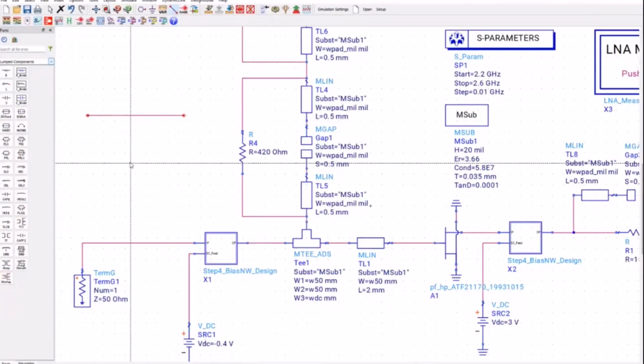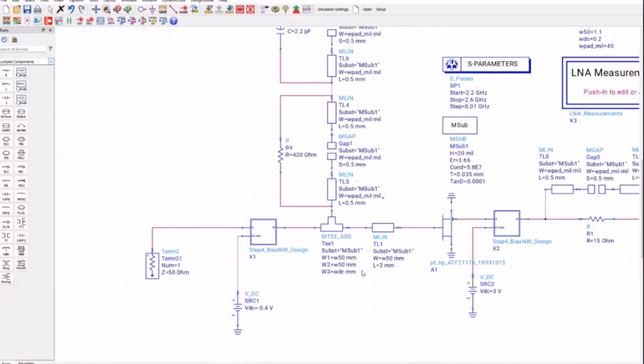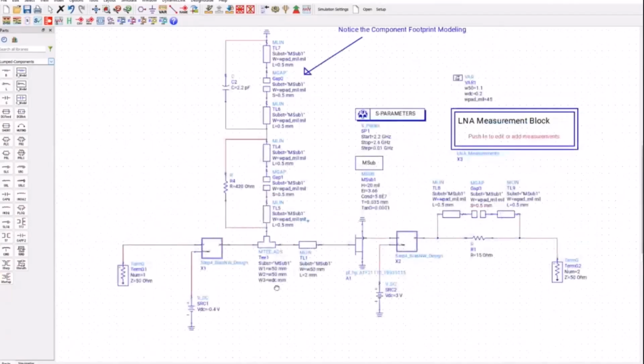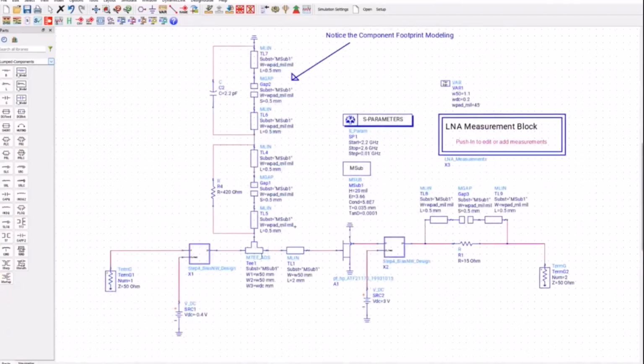Never do that. Because if you do something like this, that's fine, but then you are missing this entire discontinuity effect, because now you have a T junction. Never do this, because then you never see the right reflection. So everything which you are doing is not going to work in real life. So start implementing and account for this discontinuity from the very beginning.